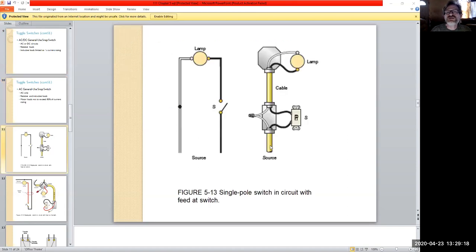So just little things. It's an interesting little chapter. They even give you some common configurations. So notice, we have the neutral side. There's no breaks in that. So where's the switch? It's on the hot side to interrupt. And then the picture shows you a common lighting configuration, how you would wire it in.